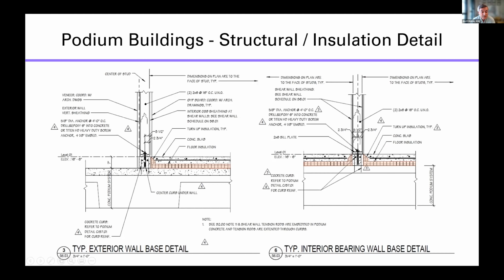And so we've done this. We treat it kind of like a slab on grade. We just put insulation that's not super stiff, but stiff enough so it doesn't cause problems, to insulate and isolate the interior finished heated space from the outside, the unconditioned space below.